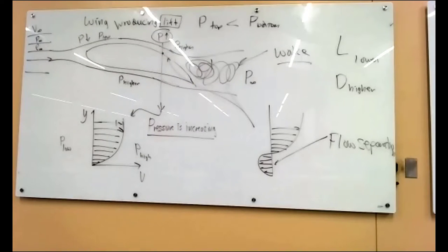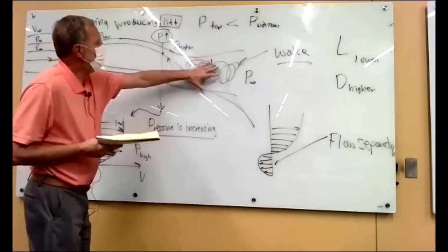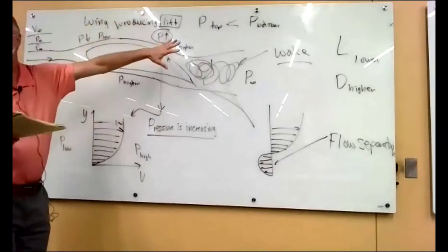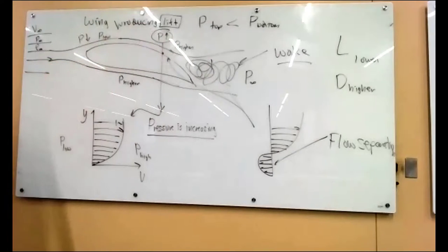That's a different effect, but because typically you deploy the flaps, you don't get that much separation. They're designed not to. But it's the additional lift and the drag that you get from the lift. But if you deploy the flaps enough, you can cause this kind of separation, and then you get a lot of drag. So with the separation and stall is when this separated region covers most of the airfoil, then the wing has lost almost all of its lift, and that's why stall is bad.